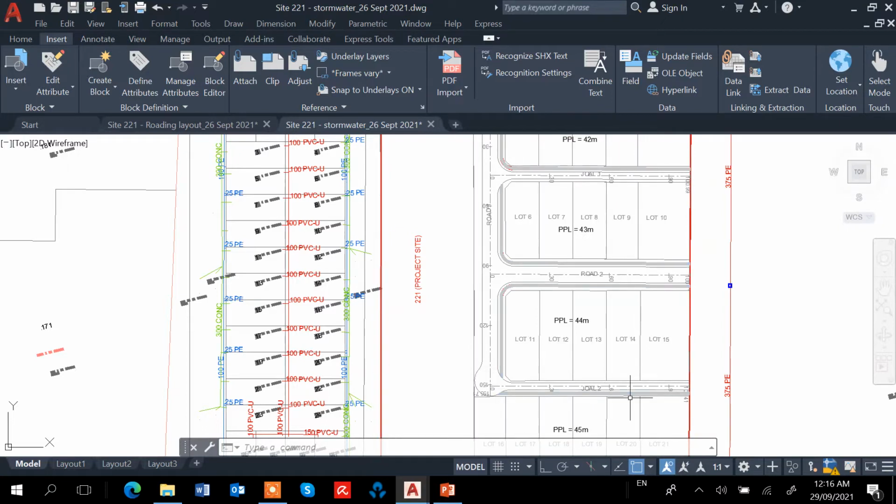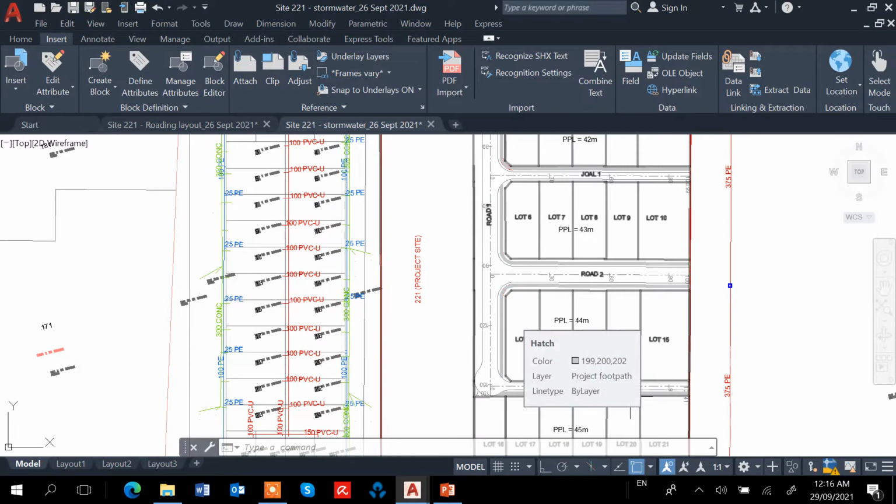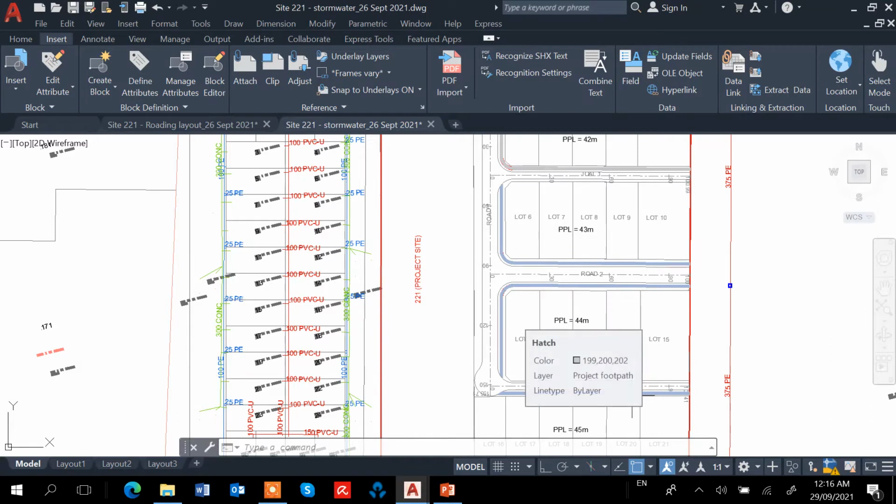But this one I'm going to use 1 in 200. Okay, I showed it the example. 1 in 200. I use two charts. One is Colebrook-White. The other one is the maintenance chart. So they give me similar results.